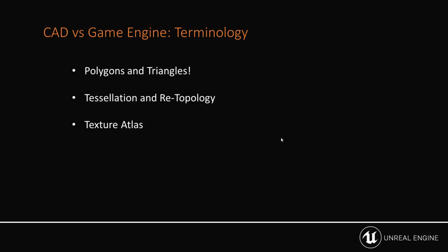Texture atlasing. Well, this is something that touches upon the idea of having textures. You may have dozens of textures or perhaps even thousands of them. That can bog down the performance of your game or your visualization within Unreal Engine. So working with a texture atlas is a way to take advantage of one sheet and place many textures on there. So this many to one idea, rather than having, say, for example, a dozen textures on all different sheets or different texture images.